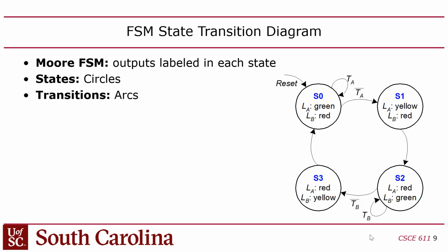As I mentioned, it's more commonly the case that you would be designing state machines to control arithmetic in a circuit, right? For example, I don't know if you guys remember this, but I mentioned, why don't we have a divide instruction in the ALU? Because if you do a divide, it would most likely be a multi-cycle divide, right? It would divide A divided by B on your ALU, but it couldn't be done in one cycle, because doing a divide in one cycle would be very expensive, it would take a long time to synthesize, and it might eat up your whole FPGA.